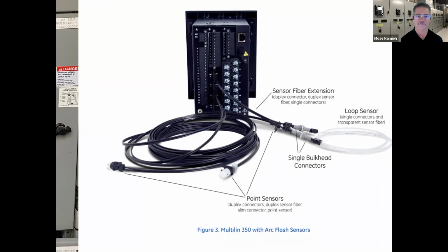And so these relays, if they get those two inputs, an overcurrent event and a light event, they trip very, very fast. So what might normally be a little bit longer fault, waiting for the overcurrent to clear, it says, no, it's not only an overcurrent, it's actually an arc flash event. Let's clear even faster.